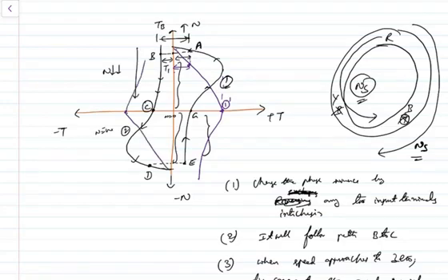So this is my curve. Corresponding to this point, it will shift from this point to this point. You can see here the amount of braking torque now produced will be this much, the new braking torque. That is the advantage of inserting the external resistance. Corresponding to this braking torque, it will go on passing. Whenever it reaches the point C dash, we have to stop the motor.